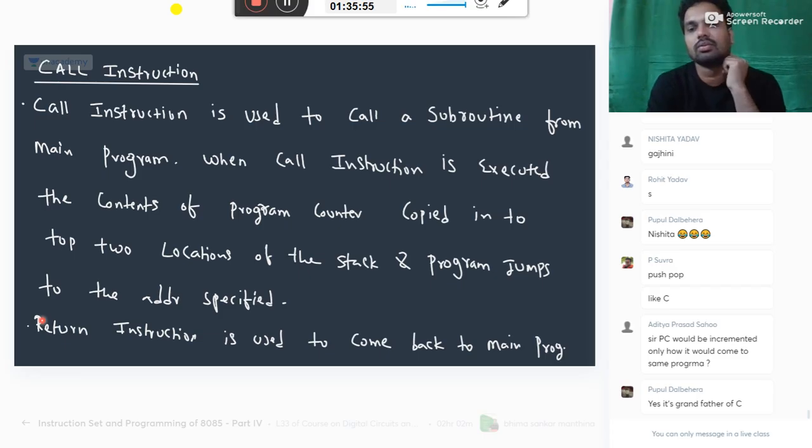Wait, Aditya, don't worry much. Here, for example, you said call. This is your first PC. PC plus 1, plus 2, plus 3. This PC plus 3 is stored into the stack. Then when you return, you go to PC plus 3. That is where your next instruction is present.